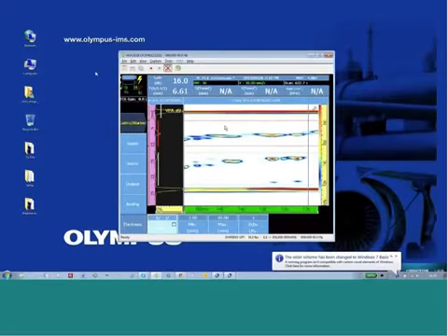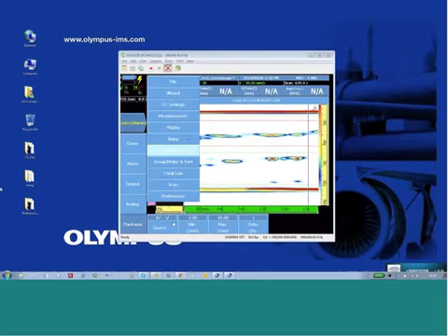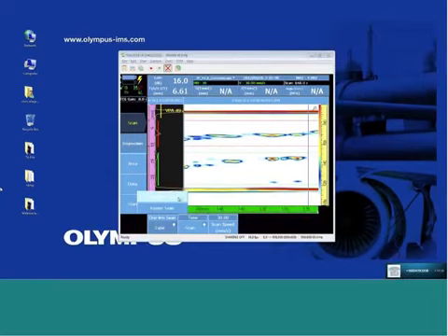Back to the desktop and live on the instrument. Those parameters regarding the C-scan can be found under the Scan menu here. For a one-line scan, meaning that we're not going to be building individual lines together with a two-axis or manual one-axis scanner, it's simply the width under the probe. The time C-scan on the clock will move at about 30 millimeters per second.